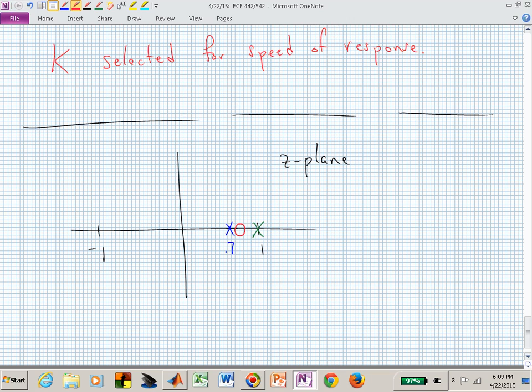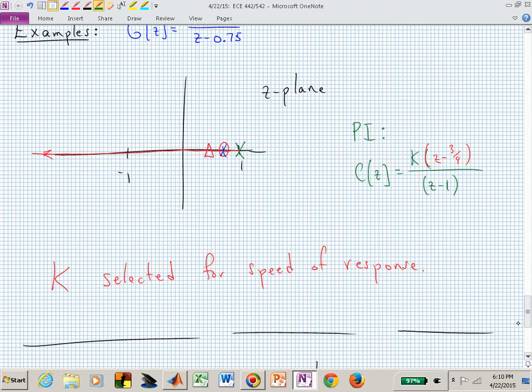This root locus, this guy goes there, and this guy goes there. And maybe for the choice of gain K that you've picked up above, maybe now your closed loop pole is here and right there. So that closed loop pole is nearly canceled by that 0, and you really just have the dynamics of that sort of isolated triangle interior to 0.7. So this system would behave almost the same as what this one did. Your design is fairly robust, your controller design.